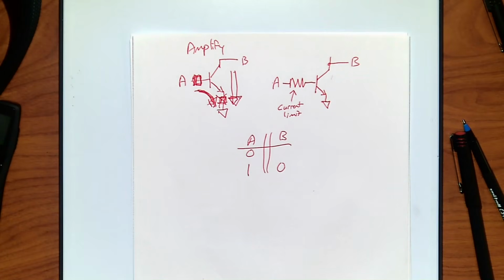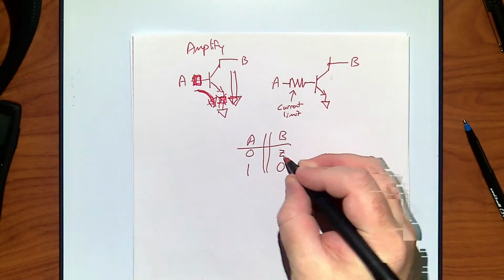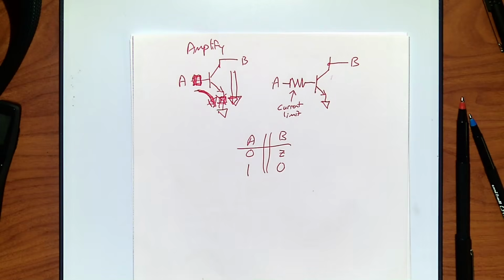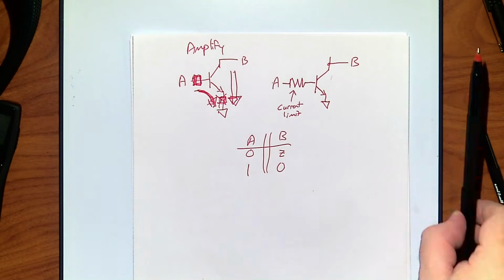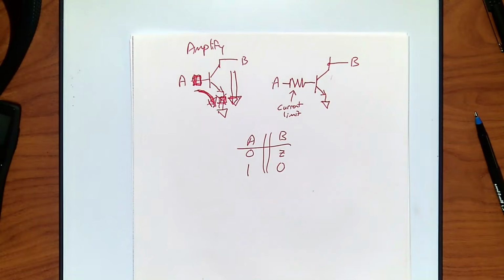Yeah, it's very good. So we can now say we don't know what's hooked up to it at this moment, because all we've done is unhooked it from everything we have. So this is, in essence, what we would call Z, high impedance. Okay? Now, if I were to put a pull-up resistor on B, it wouldn't affect the ground, would it? No, not as long as you pick a decent value, over like 500 ohms, you'll have no problems, right? But if it's disconnected, what's going to happen? When you've got a voltage up there, that becomes a 1.